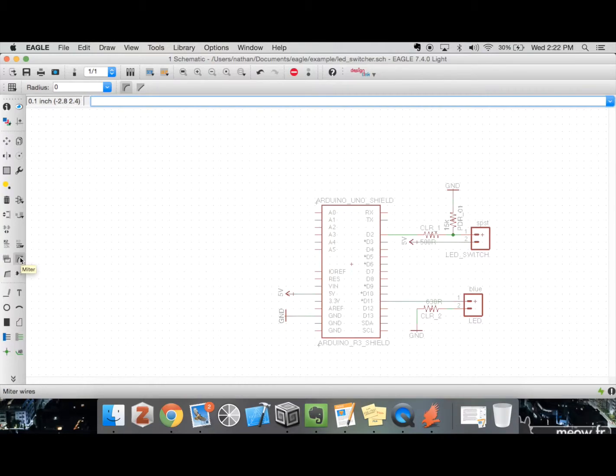Which is something that I've never really used, so I assume it's something that you're not going to really need to use either. I also have split and bend align, which is basically you can create these breakpoints and then modify your nets. And then we also have invoke, which is a way to do cleaner routing of gates. Once again, something that doesn't really come up.